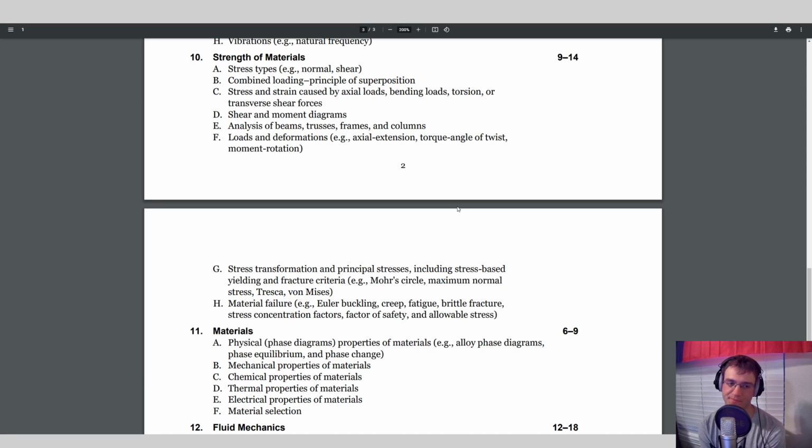When you look at the bolts that hold your wheel in place on your car, that's something that fails due to fatigue over time, because it's going through stress cycles depending on what position it's in relative to the rest of the car. It's going to have a different kind of load on it, and as you drive, it cycles through its load over and over, and that can shorten the failure time depending on how many cycles you go through.